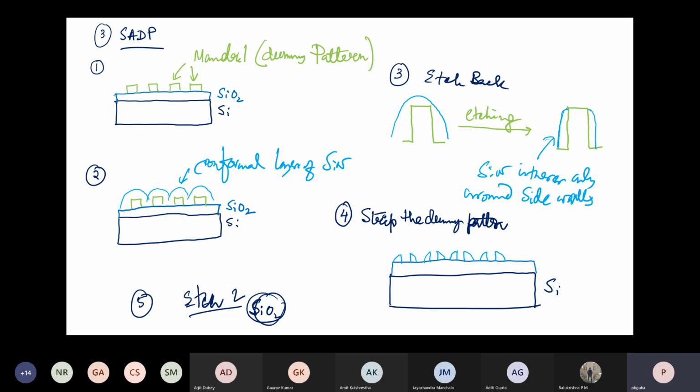We see double patterning in our design, right? But along with double patterning, we can have even much more using the same design. Okay, for example, we can have triple patterning, we can have 4 times patterning, 8 times patterning, and so on. Now double patterning gives two times the pattern density that we have seen.